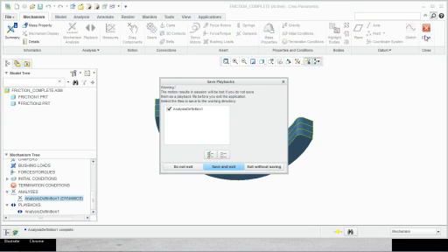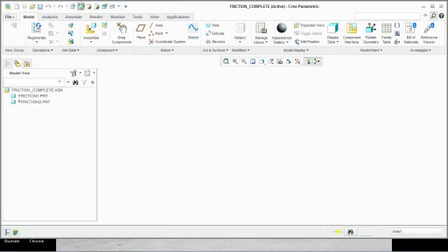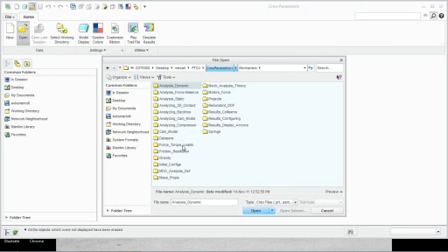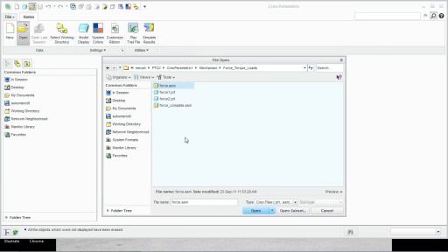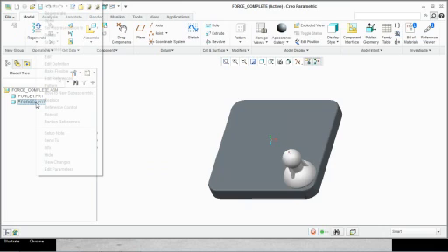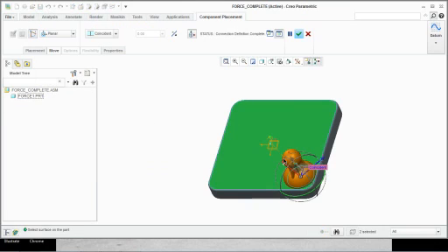All right, that being said, let's talk about applying forces. So I want to apply a force or a torque. How do I do that? I have a simple example. Note that this little part is connected by a planar joint. That means it can rotate and translate along this surface, but cannot move away from the surface. All right, so let's get into mechanism.